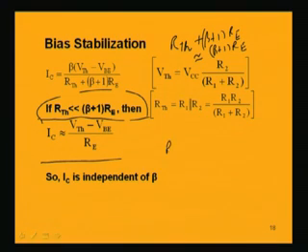You cannot have RB very small, because IB will also be increasing, and there is a limiting condition for every transistor, which is very much specified in the data sheets, such as limiting power, etc. So, actually we are not free to choose any value, but within the limitations we can choose better values to make this condition satisfied, and it is better to have two resistances R1 and R2. We can choose the combination in order to meet this specification rather than deciding on a single resistance RB as was done earlier.